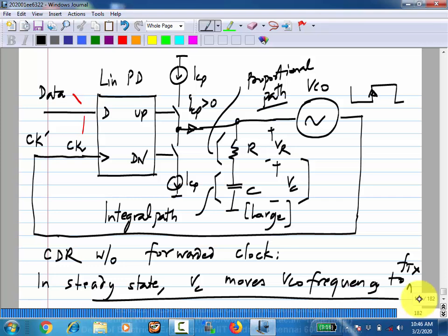That is essentially your repeating bits. It will stay locked, right? Meaning, at 10 gigabits per second, the clock was in the center of the data. That means this will give you a zero average output. Then you are transmitting like this. But then at 10 gigabits per second, you start repeating every bit twice. Every 1 or every 0, you repeat it twice. It's actually 5 gigabits per second data.